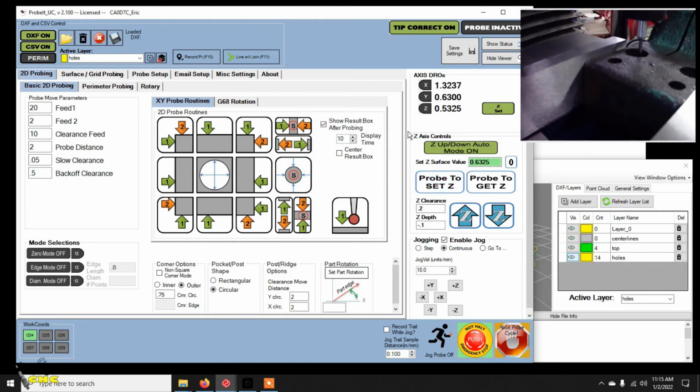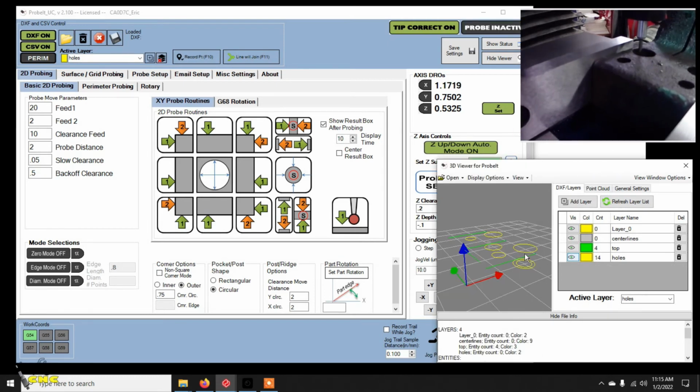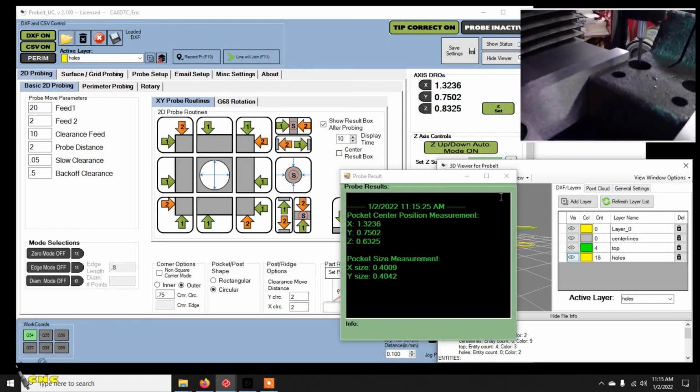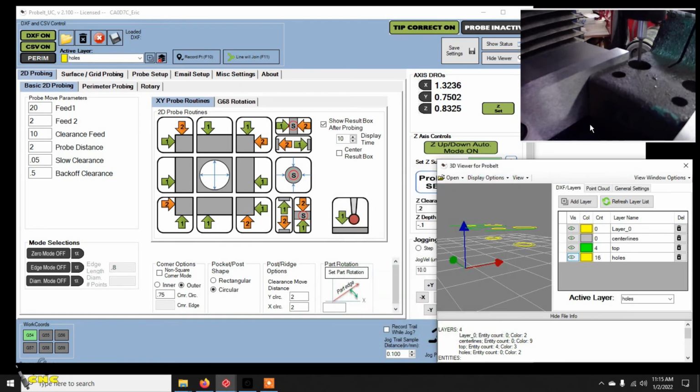So it appears not too intuitive the way the buttons are set up here, but they are there with a purpose, so that you can get various depth level measurements and record values at a height which is not the same as where the ball is, because obviously you want to know where the surface is in real space, but the ball has to be above or below it to get the actual geometry. So that pretty much maps out all the hole features on this side.